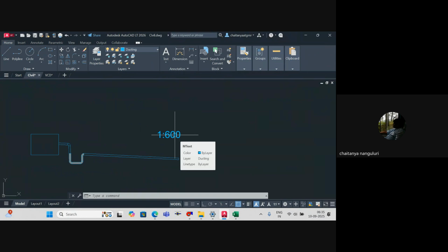But because it's only drain, you don't have any solids, whereas normal plumbing drain means you have some solids or anything. But in this case, it's just condensate water that will go. You agree? So for that reason, the slope of 1 is to 600 is also worst case is fine. Understood? No, 1:100 is normal.